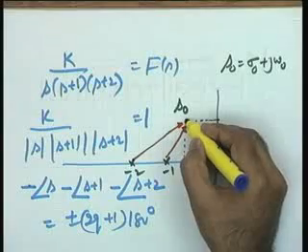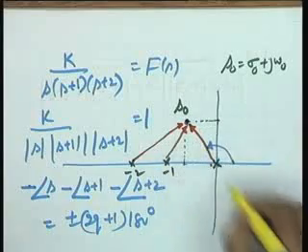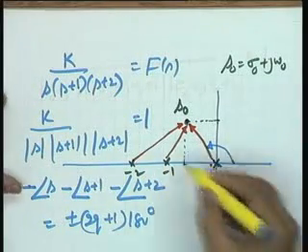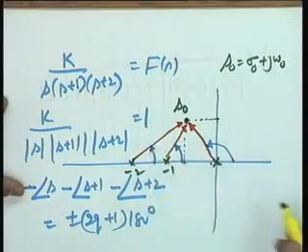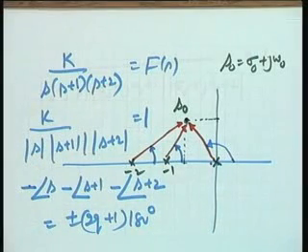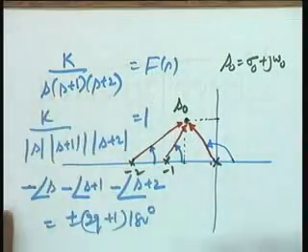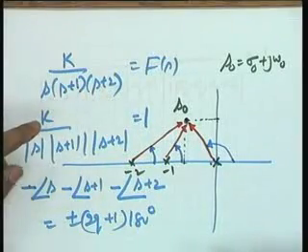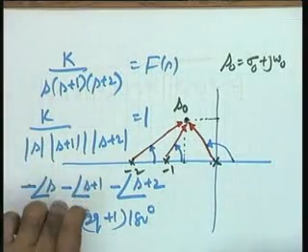Okay. So at this particular point, if you are testing, what is the net angle contribution as far as this particular pole is concerned? Yes, this angle you calculate for s plus 1, this angle you calculate. So these are the angles contributed by these particular factors. If you take the sum of these angles with a negative sign, because these angles are in the denominator, when they come to the numerator they will appear with a negative sign.